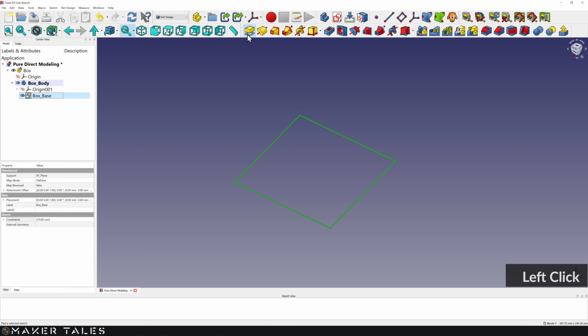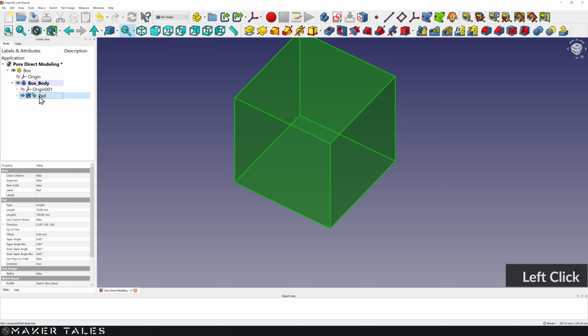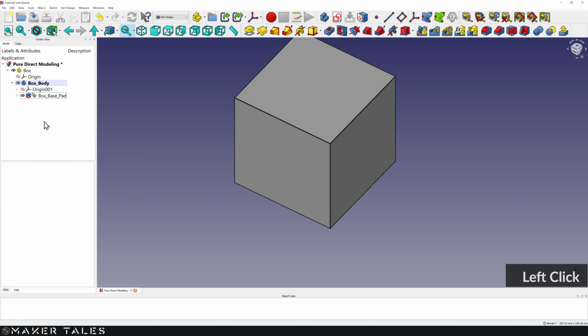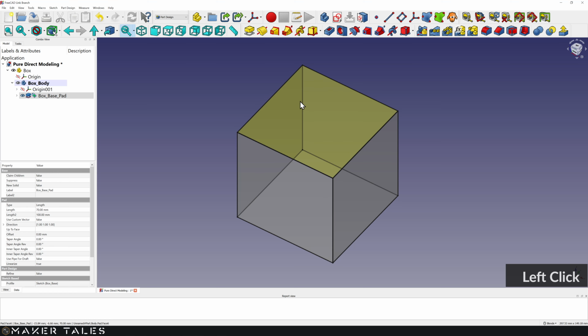We're going to pad this out. We can see that this should be 70 from the technical drawing. We'll click OK and rename that pad. So keeping the pad this time though, but I'm going to go with box_base and underscore. So this way I know that it's the box base sketch and that the pad is deriving from that sketch. Okay, now let's go and create this pocket.